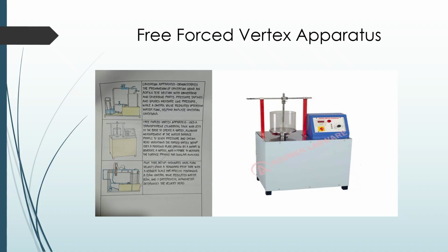This experimental procedure involves measurement of the resulting free surface that is calculated by the variation of the sum of the pressure head and datum head. A drain pipe is provided to drain the vessel when not in use.